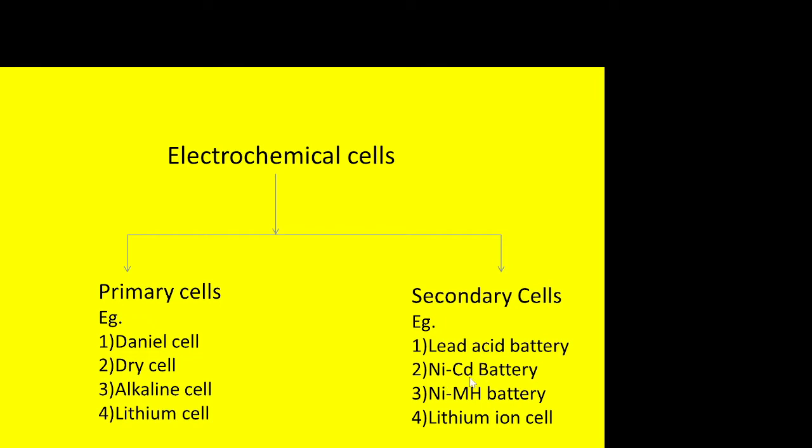Nickel cadmium batteries were used about 20 years back. This type of battery is not there in the market now. This battery has an EMF of about 1.2 volt. It has very low internal resistance. We can draw very high current from such a nickel cadmium battery, though the voltage is only 1.2 volt. This type of battery was used where a very high discharge rate is required.